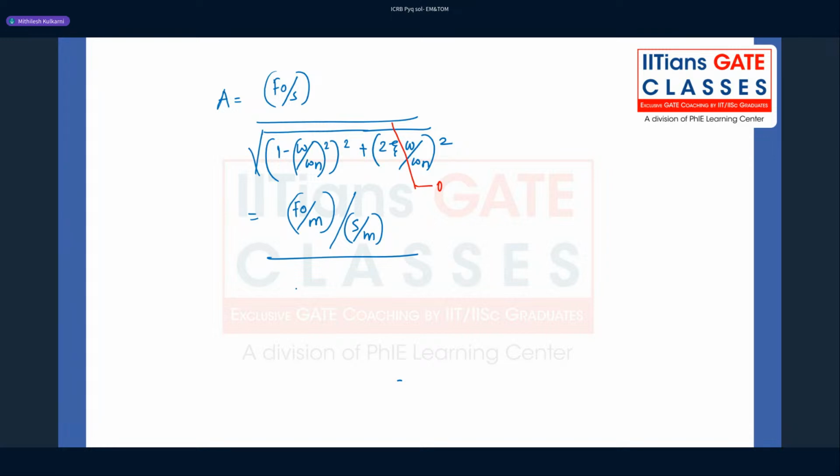And in the denominator, we'll have 1 minus omega by omega n whole square, under root, and the square of the whole term cancels. F naught by m is what? F is equal to ma. So this is about the acceleration. And S by m is the natural frequency square, divided by 1 minus omega by omega n bracket square.